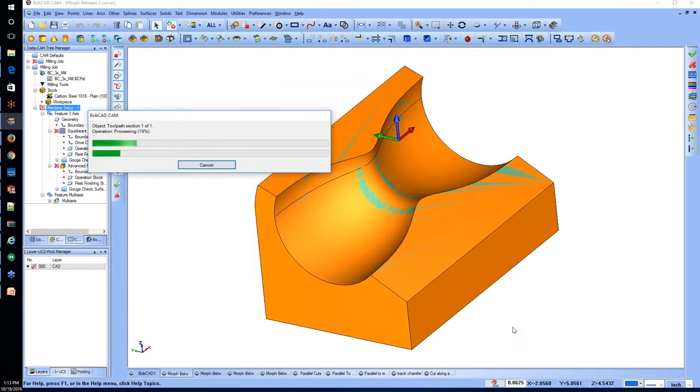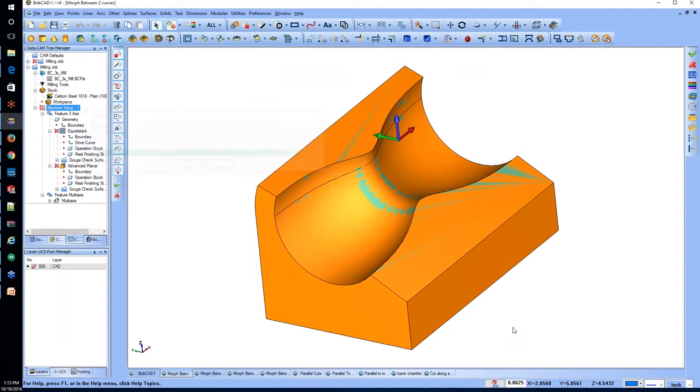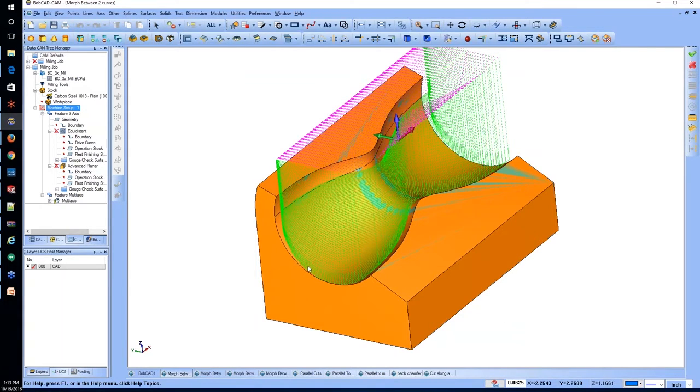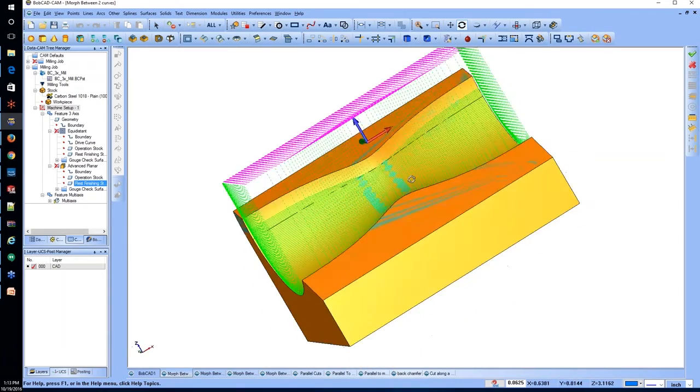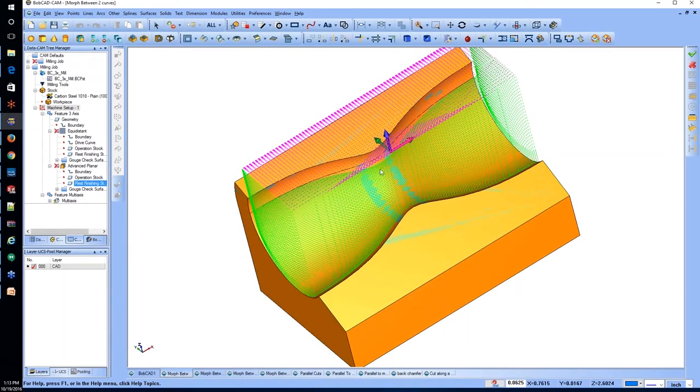Let's see what we get, and then we will adjust the toolpath as needed. Now, these particular toolpaths, there's a lot of different settings that can alter the toolpath. Normally, what I try to do is get a baseline toolpath that looks somewhat right, and then I alter it from there. Okay. So as we can see there, that's not a bad toolpath right there. There's a lot of rapids. So to fix those rapids, we can actually turn on zigzag.